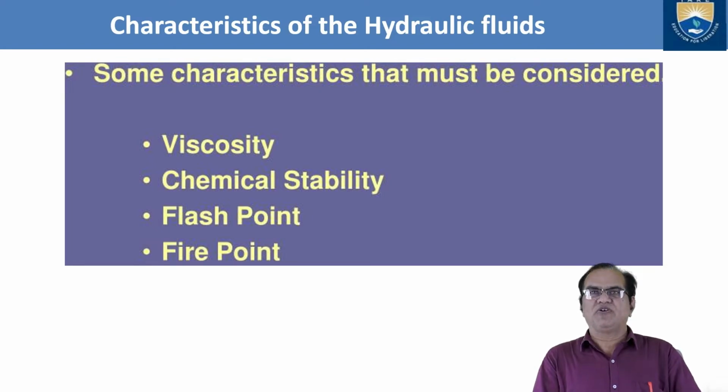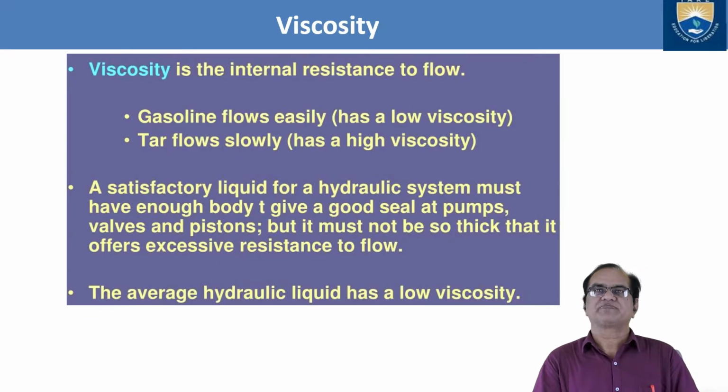Characteristics of the hydraulic fluids. Some very important characteristics that must be considered are the viscosity, chemical stability, flash point, and fire point. Now I will discuss each one by one. Viscosity is the internal resistance to flow. So what is viscosity? Viscosity is the internal resistance to flow.